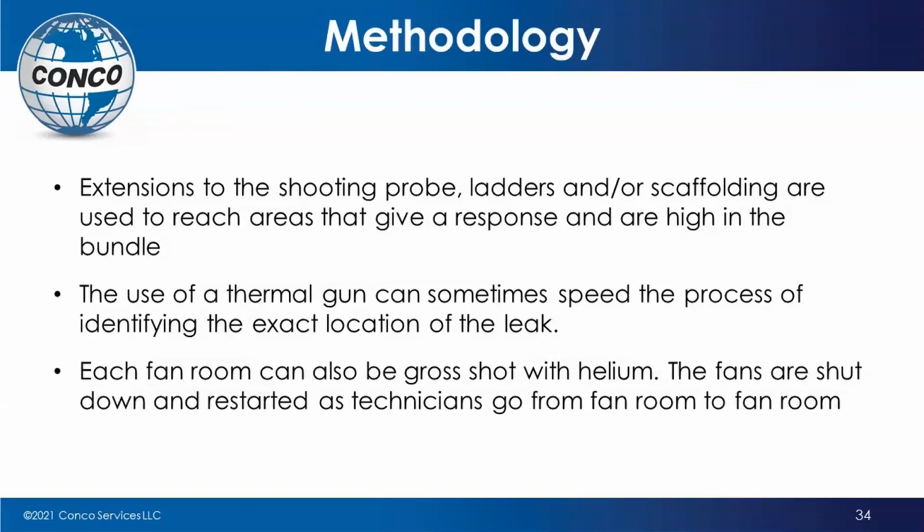We use thermal guns at times. What that does is give us a good idea, if the leak is big enough, of the general direction of where the leak is, and then we can get up there with the helium. And in some instances, if available, if we're able to shut down a fan room, we can do a gross shot of helium into a fan room to get an idea, are there any leaks in this particular case? So there's a couple different tools that we use. This, again, comes with experience.